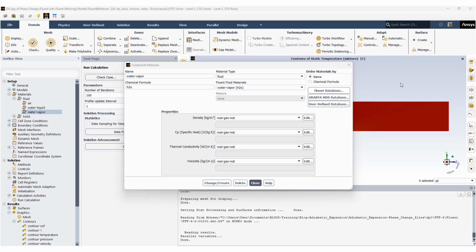You have to know that the results that I showed you so far all depend on the operating conditions, the parameters for the geometry and the materials, and also the inputs for the boundary conditions. For example, I considered 1 kilogram per second for the mass inlet, but if you change it to a much smaller one, you may not see the phase change. If you go to, for example, 0.5, maybe you can see just a much smaller amount of condensation right at the front of the opening.